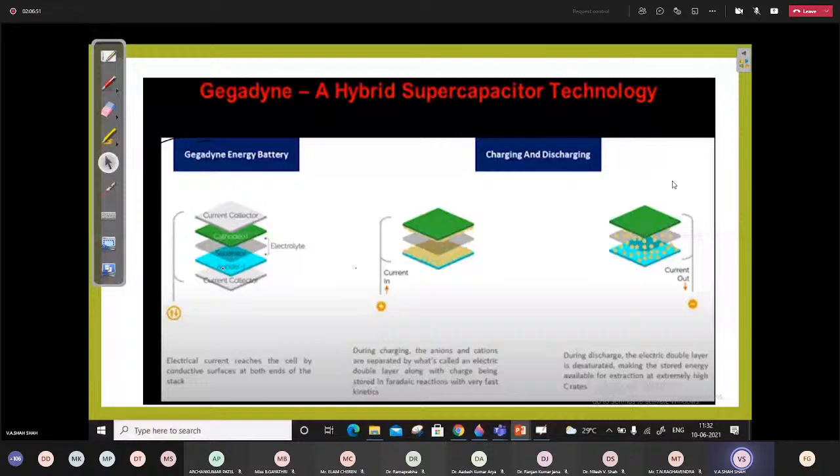You can see here initially the supercapacitor is supplying power, and after that the battery comes into the picture and supplies power during this period. And it may provide power to the supercapacitor also. So the supercapacitor gets charged through the battery, because, as we know, the battery terminal voltage won't get reduced as it supplies power to the load. This is in a larger form. So the green is supercapacitor power and this is the battery power. And here the capacitor gets charged by the battery.